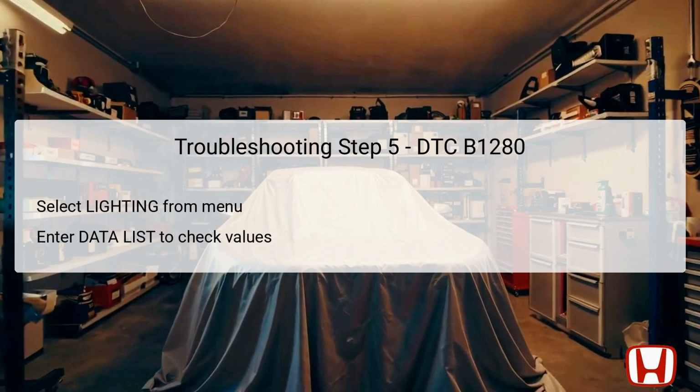Step 5 involves selecting the lighting option from the Body Electrical System Select menu in the HDS. From here, you will enter the data list to monitor the values pertaining to the turn signal switch. This data provides crucial insights into whether the turn signal switch is functioning within the expected parameters. Evaluating the data list allows you to see if the switch delivers outputs that match its position. On for left when switched to left.